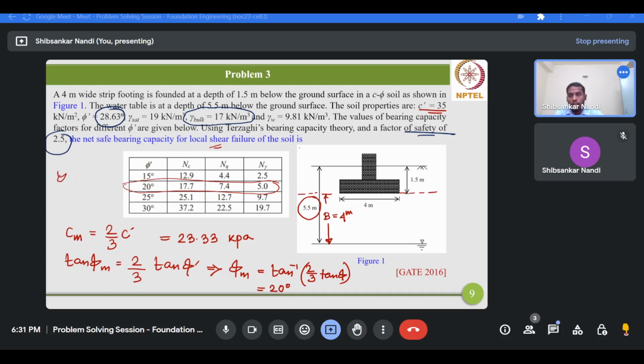Okay, so where this angle of internal friction value is less than 29 degree, and general shear failure will govern when the angle of internal friction value is greater than 36 degree, and in between you have to consider a mixed type of case, that is you have to consider both general and local, and then interpolate the values. So mixed type of behavior you can expect. Now this is only for the purely cohesionless deposit. Now for this problem it is not purely cohesionless, so it's a cohesive frictional deposit.